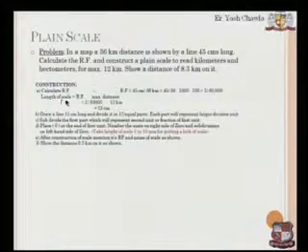So this is my RF factor. Now I'll take out the length of the scale. The length of the scale is RF, that is representative factor, into maximum distance. So the maximum distance is 12 kilometers, so I'll have my representative factor multiplied by 12, so it comes down to 15 centimeters. So how are we going to draw this particular scale? Let us take a look at the figure which is going to appear on the bottom side and know how we are going to draw this particular scale.